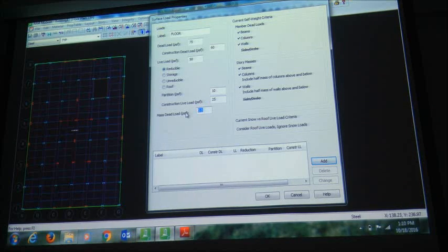Mass dead load is basically our total dead load which is responsible for seismic load. By this time in your 488, I'm not sure whether you have done seismic base shear calculation. Have you done that? Okay. Anyway, seismic loads are basically a proportion of your self weight. It's an inertia force, right? Why?